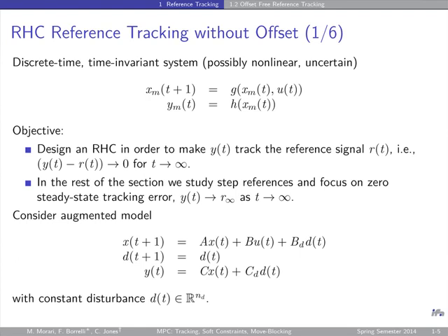In that lecture, you have a little bit more detail on this material, namely that you augment the system state with a disturbance state, and this is now what I will estimate using my estimator that I showed you already on the next slide. What the estimator does is the same estimation principle that we introduced. On the top I have exactly my model from the last slide, except that now I have an X hat and a D hat, which means my estimated state and disturbance.